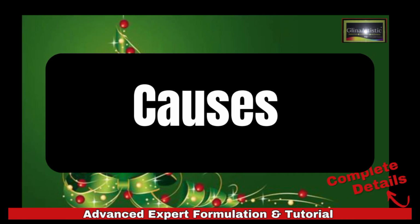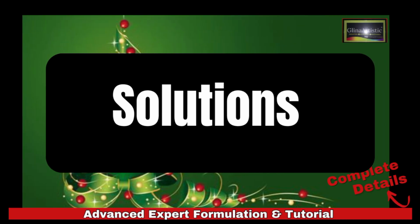So what are the causes? Insufficient pigment or low quality fillers, which are your titanium dioxide or your calcium carbonate. So now the solution is simple: increase your pigment concentration, especially titanium dioxide, during your production, and of course use high opacity fillers like calcium carbonate.